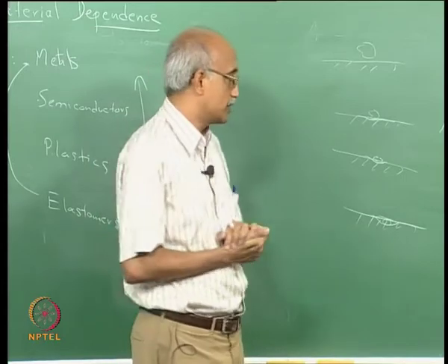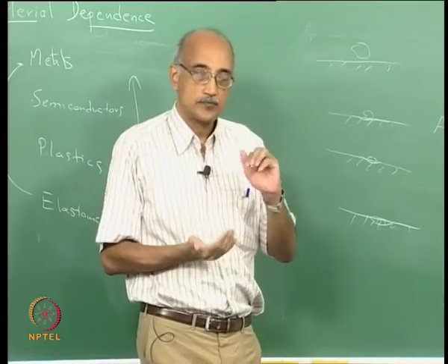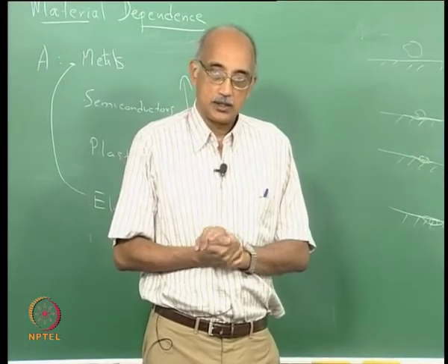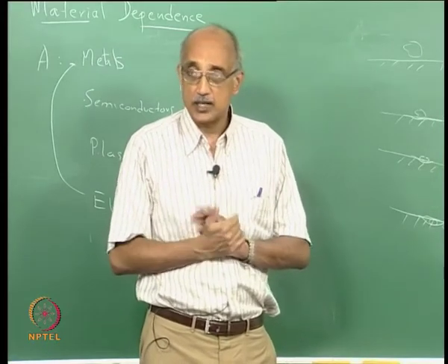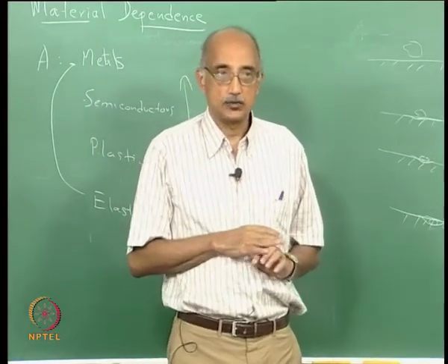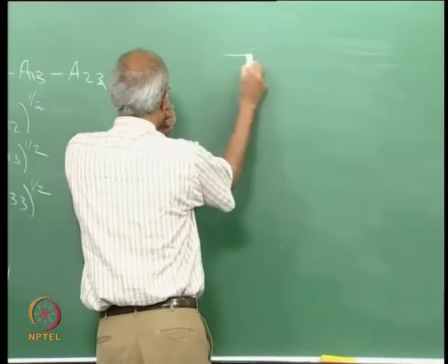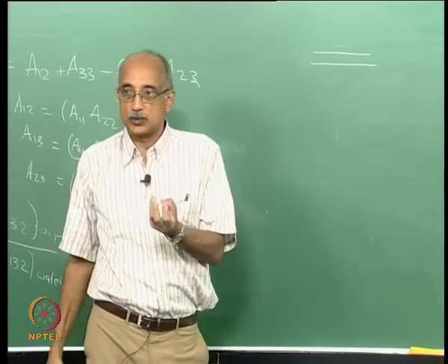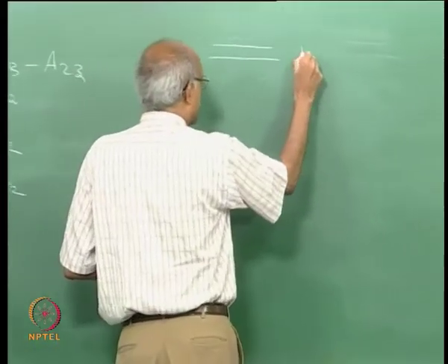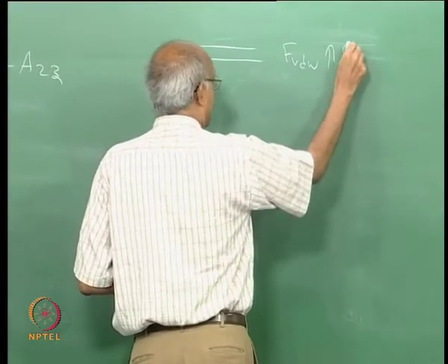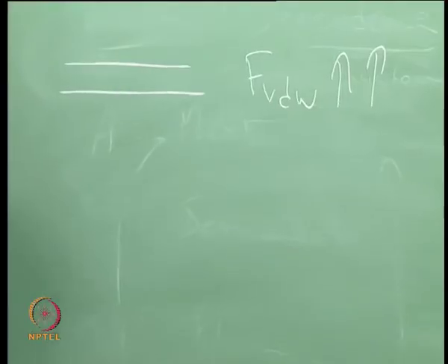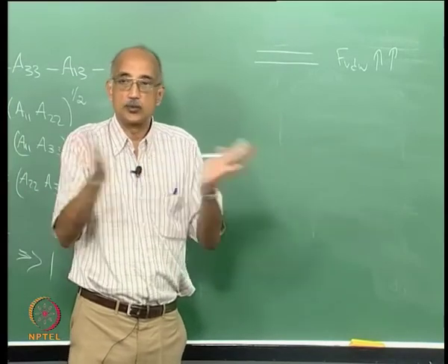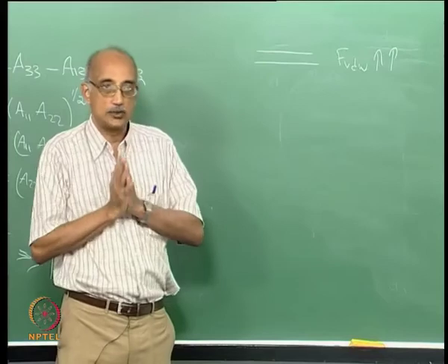And in fact some of these same arguments apply for roughness also. When you have two smooth surfaces contacting each other versus two rough surfaces, again the adhesion forces are different, and the reason for that again is the differences in the area of contact more than anything else. So when you have two smooth surfaces that come in contact or a highly polished particle that is approaching a surface, the van der Waals force is very high. In fact I'm sure you have heard of the experiment where you bring two highly polished surfaces together, you can almost never take them apart. The forces of adhesion are virtually infinite.